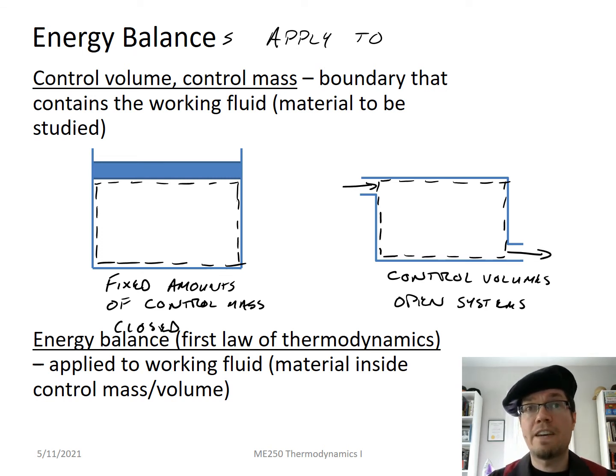So it is not a fixed amount of mass, it is not the same chunk of mass, it is a fixed volume. That volume might deform, that volume might move, but it is a fixed volume and things can flow in and out of it. And so energy balances, the first law of thermodynamics, apply to the working fluid or material inside the control mass or the control volume. That's the topic of today.